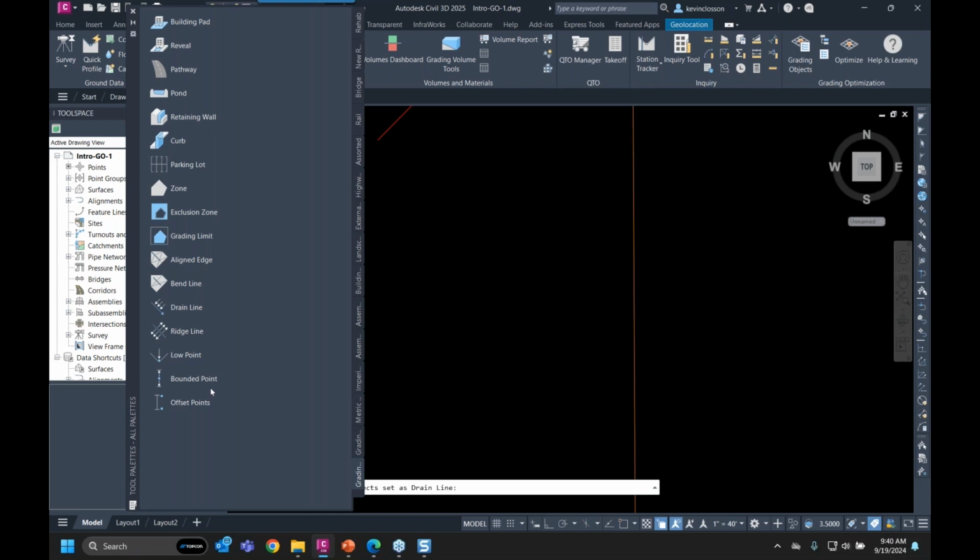And then once you go into it, everything looks okay, but there's a specific area here or there where a catch basin needs to pull those triangles down a little bit. So we'll place a point, add it to the surface, and sometimes manually you can do it by putting some labels on it, slope labels, and raising and lowering that point. And when that surface updates, you can see what we're doing, if we're getting the appropriate slopes and that kind of thing. So that's what that low point is. It's a key location somewhere that we want to hold.